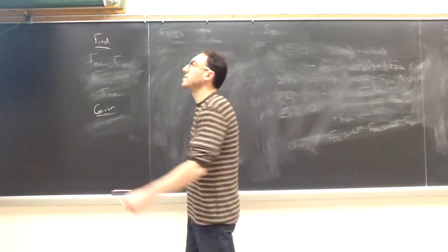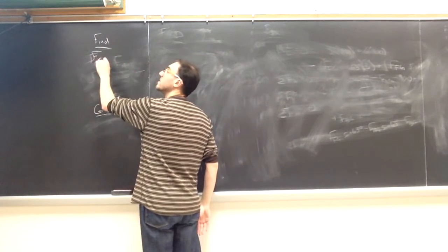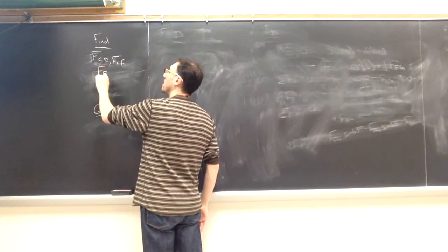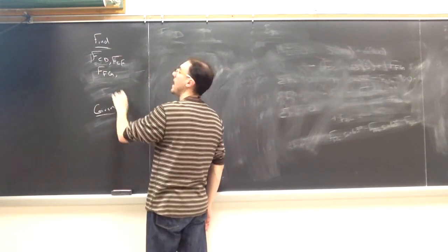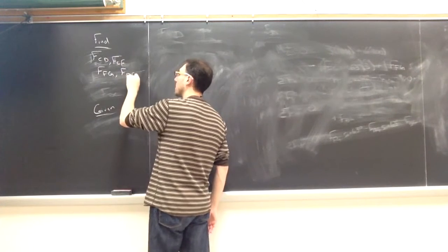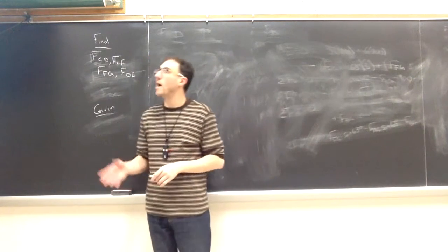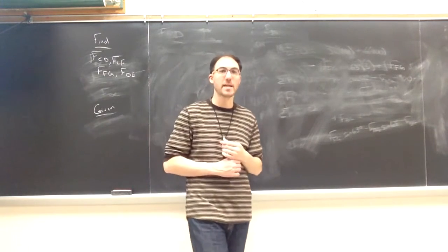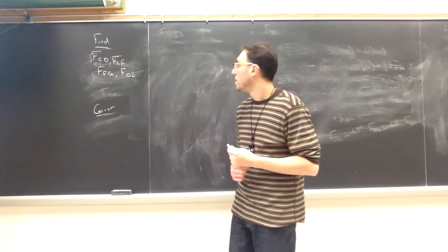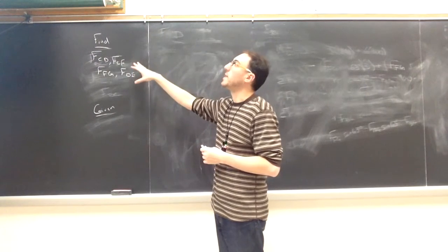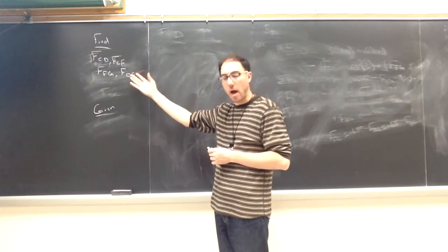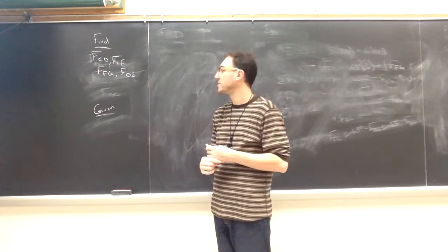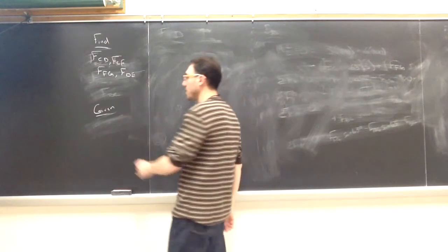We are only asked to find the forces in CD, CF, FG, and DE. So we want 4 of the total of the 10 or so members that make up this truss. Right away, this is an indication that we probably want to make at least one section cut in our solution process. And we're given just the diagram.